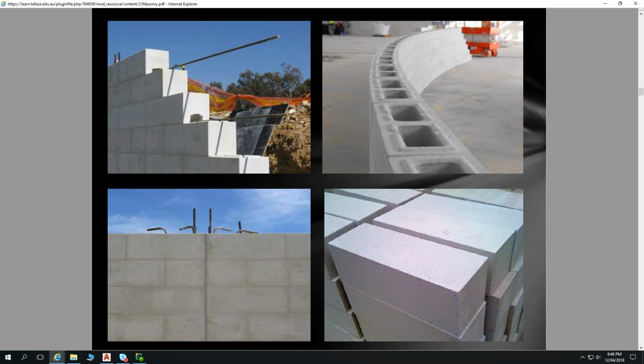And so the different concrete properties possibly flow into why our Besser blocks have a slightly different colour. But if you're a stickler and you really want that colour, because that colour works well, we just want natural faced Besser blocks, and we want it to work with certain colours, be aware of that. That's a winter time. That's a summertime. There's some Hebel down there.